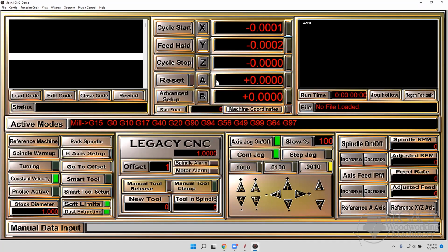If you don't have a proximity pad, then that time delay is definitely the only thing we could play with to get it to work. It just waits for how long. If you said wait 1 second, it has to be on for 1 second before you get a real signal, so it's driving for a full 1 second. It's going to be set in nanoseconds, but we can reduce that and maybe help you out. So contact Mosiah, and if he has questions, he can contact me and I'll help him out. But I think he knows how to do it.